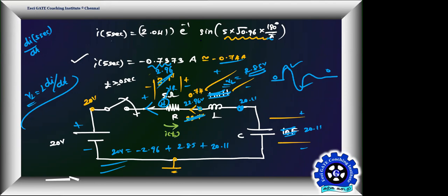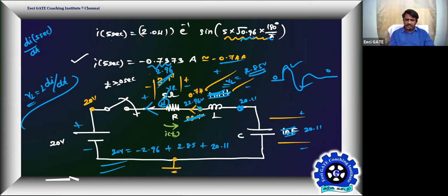L and C values are included in our omega n and omega d, so we didn't change them. So the responses won't change because of them. Only the response which is exploiting the resistance value will change. So resistance is 4, therefore it can change.